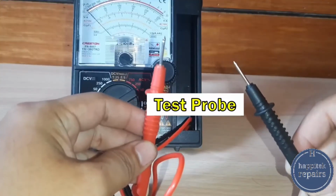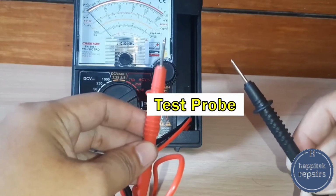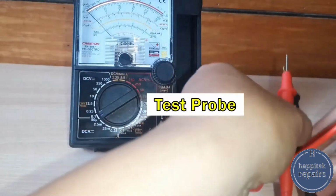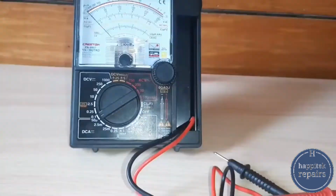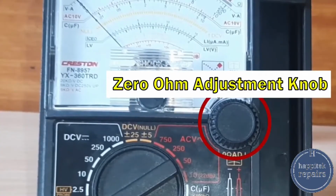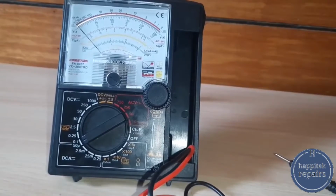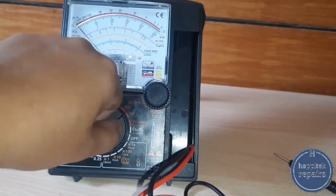These are the test probes. We use them to place on the device or component we are measuring. And lastly, the 0 ohms adjustment knob. For example, when using the ohmmeter, we need to adjust it to calibrate our meter.